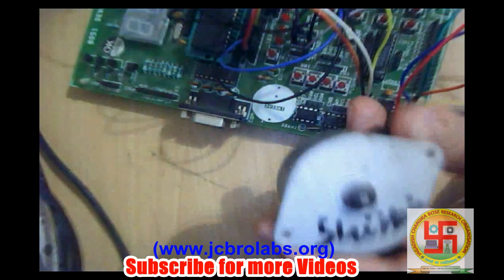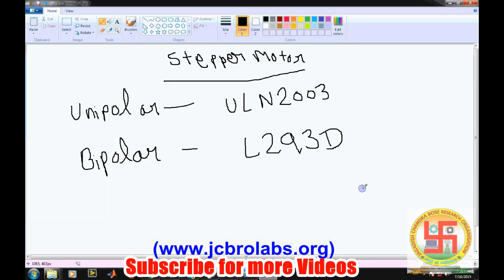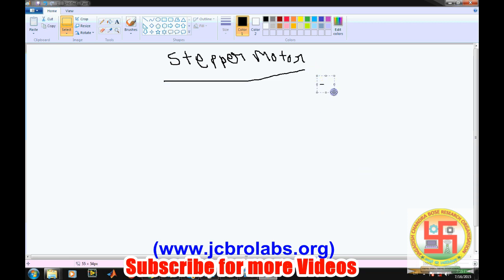So let's go back to theory and learn how to write a program to run this particular stepper motor stepwise. So you have seen the kinds of stepper motor, unipolar and bipolar, and the identification of these two can be done by the number of wires which are coming out from these stepper motors. Now when we talk about running of this stepper motor, as we say, it runs in steps. That means when power supply is connected, every manufacturer defines the step angle of these stepper motors. So it is basically based on the manufacturing.